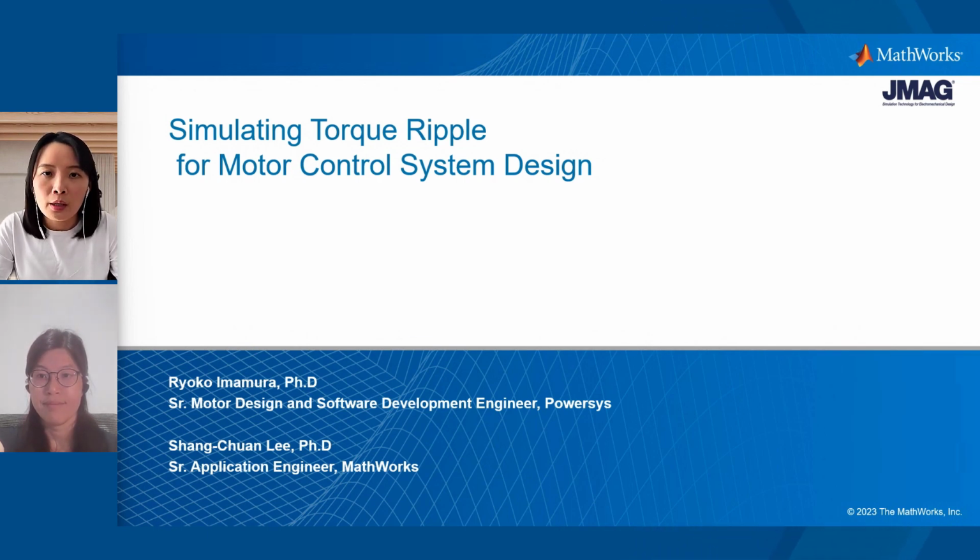So in this webinar, Ryoko and I will show you how to simulate torque ripple with a high-fidelity motor model in Simulink. Specifically, we will show you a workflow to integrate FEM JMAG motor data into Simscape Electrical. In this project, Ryoko is focused on machine design and component-level simulation by generating high-fidelity FEA motor data. After she performs the FEA analysis, she will pass the FEA data to me, and as a motor control engineer, I will work on system-level simulations to validate torque controls in Simulink.